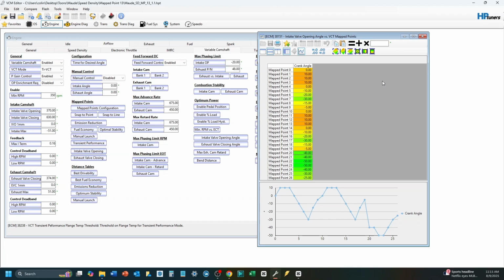I worry less about 21 through 25 simply because when you look at the logs and how this blends together, it doesn't spend a lot of time in those, and when it does, the percentages are quite low. In fact, I think it would probably be pretty challenging to try and tune those. Once I'm done with most of my speed density tables, I'm going to perform the process, and we'll give feedback. In fact, I might have a quick little, much shorter 5-10 minute video on just the optimum power WOT specifics of the method and how this all works, right?